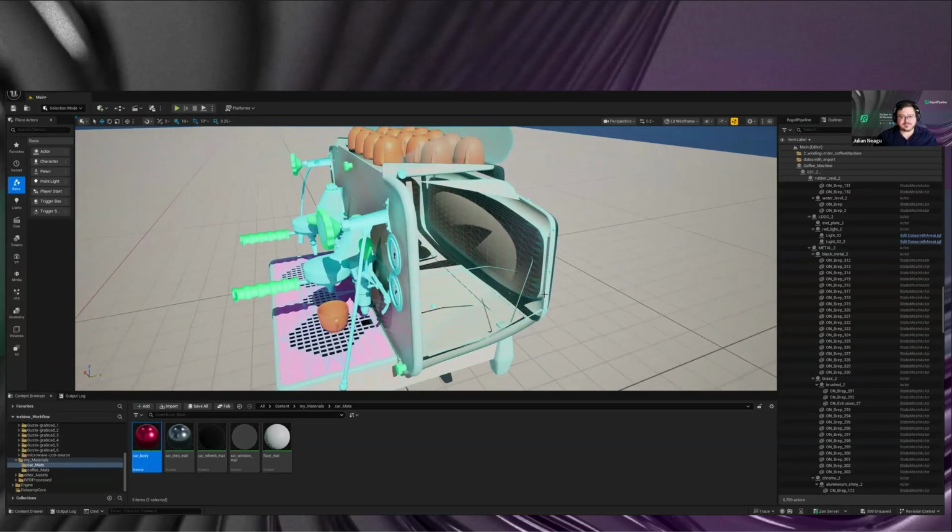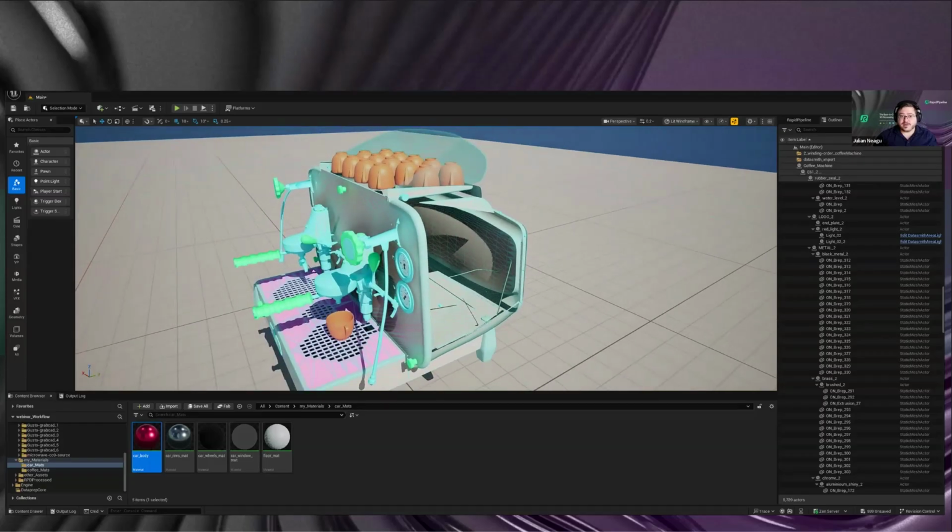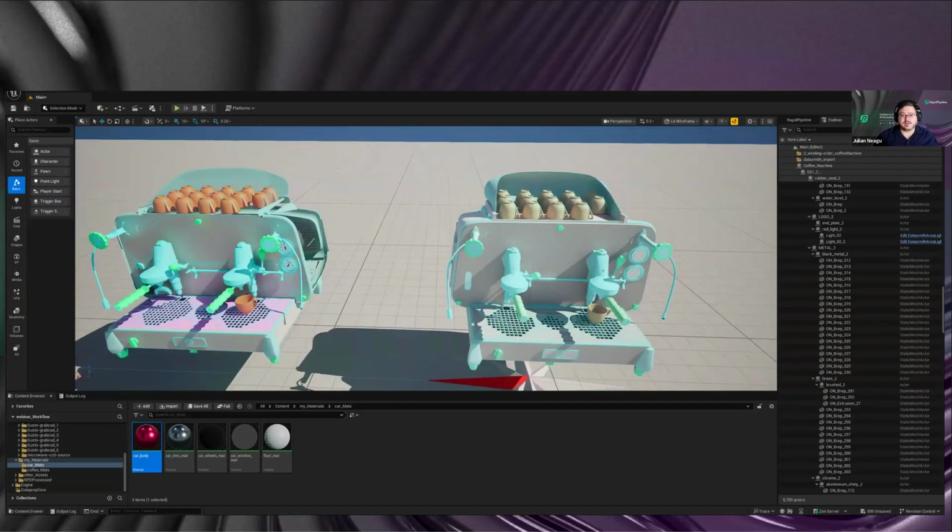Sometimes in certain renderers, you can have double-sided shading active and then you're not even realizing it. But when you, for example, use that in a game engine like Unreal Engine, and then maybe even port it to a mobile version where you only use a rasterizer as a renderer, no path tracing and no ray tracing, then it could very well be that it will be quite visible and looks pretty broken. So that's actually something which is quite important to fix and to have an eye on. In other DCCs, there are also visualization debug modes. For example, in Blender, there's a mode to visualize these winding order problems. So that's something we always recommend to keep in check, that there are no problems with that.